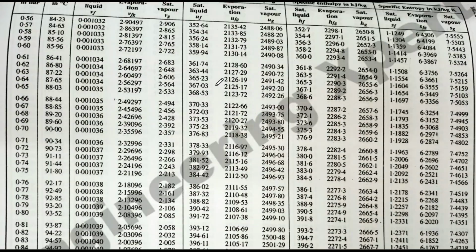You need at least two parameters to define any state. Mostly you'll be getting one of pressure and temperature and another of the given values like specific volume, specific internal energy, specific enthalpy, specific entropy. One thing to notice is that if you get pressure and temperature as the parameters, say pressure as 0.7 bar, and if the temperature is higher than 90 degrees Celsius, then it is superheated, because inside the dome during phase change there is constant pressure and temperature, and outside the dome it is constant pressure but temperature is not constant. So if the temperature is higher than the temperature at the saturated point, on the liquid or the vapor line, then it is a superheated region, else it is a subcooled region.